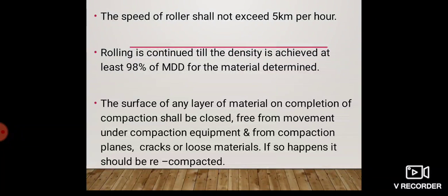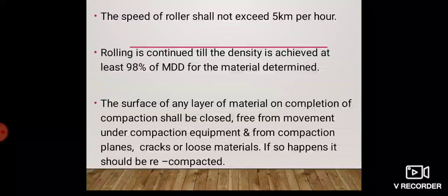Second, the laboratory compaction test. As per the Bureau of Indian Standards, heavy compaction is carried out to determine the OMC and maximum dry density. The CBR value of the selected material is determined in the laboratory. The field moisture content of the material is determined prior to compaction by any rapid test method, and the extra quantity of water to be added to bring it up to the optimum moisture content is estimated.